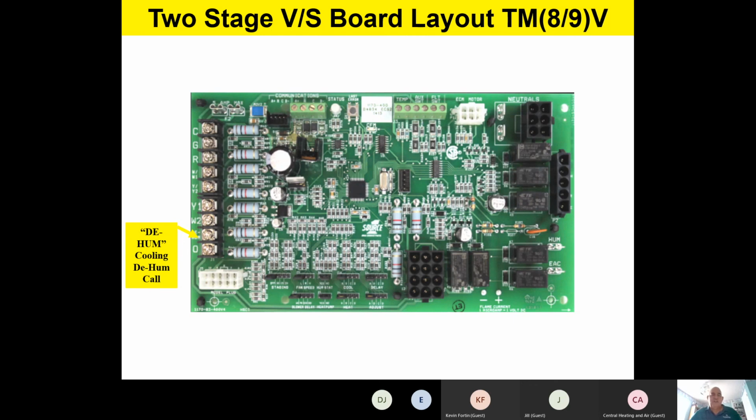This board has a dehume function, a dehumidification function in the cooling mode of operation. Because it's variable speed, if you want to have a humidifier hooked up to this dehume terminal, it'll actually dehumidify in the cooling mode of operation. So that's a pretty cool little feature.